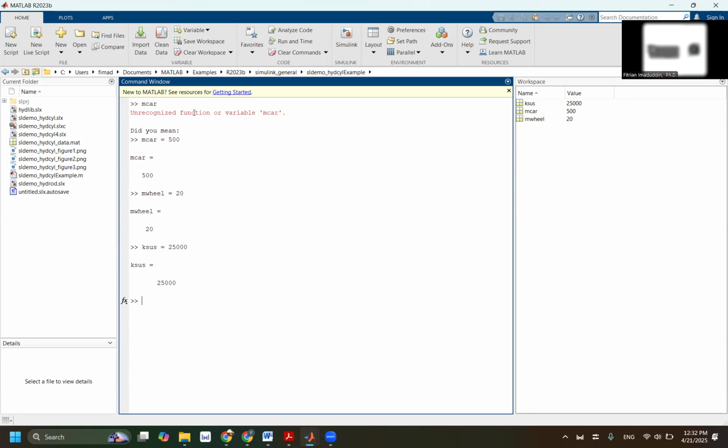The K of the wheel normally is going to be more. You can try to calculate, but the easy way is you observe the wheel, the distance between the lip of your rim to the surface of the road. Normally it's going to be really less than 1 centimeter. I'm assuming, say, the K of the wheel is like 10 times the K of the suspension. So if you loaded the same amount, it would deflect probably less than 1 centimeter, maybe 1 millimeter. Really stiff wheel, 250,000.